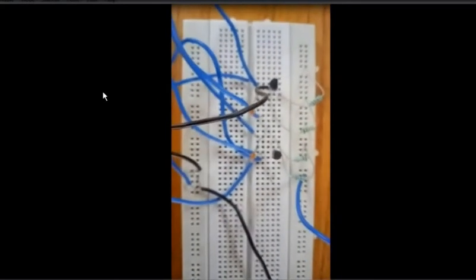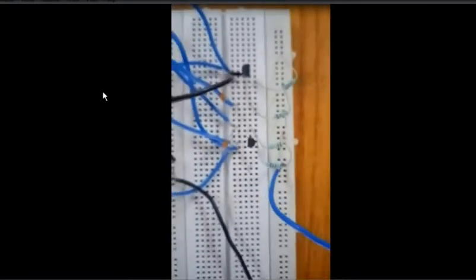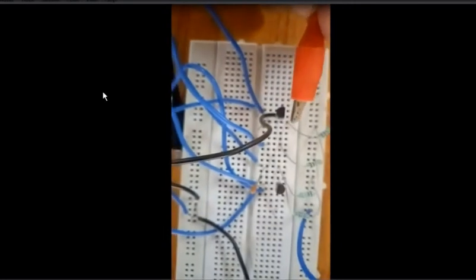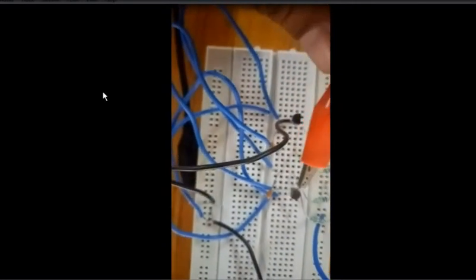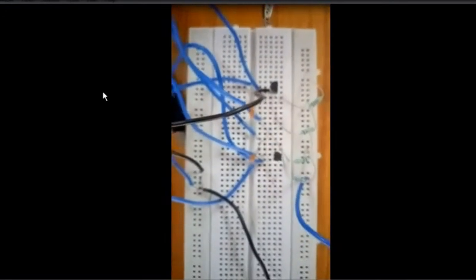For initial testing, the 0 position is kept, and then the base connection or collector side connection is taken for the analysis. Then 0.01 ceramic capacitors are connected, along with the resistances RC1, the base resistances RB1 and RB2, and the collector side resistances. These are connected to the CRO through CRO probe leads. This is a cathode ray oscilloscope, a 20 MHz cathode ray oscilloscope.